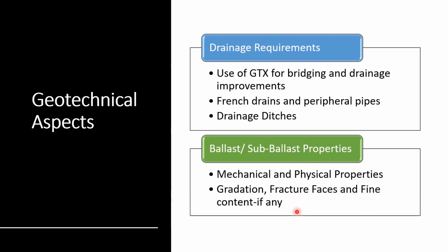The fine content is usually very, very low, less than maybe 0.5%. In some cases you're not expected to have any, but depending on the local soil, and again the project standards, sometimes they allow room for some fine content. So you have to look into that and be aware of how good or bad this would be for your design.